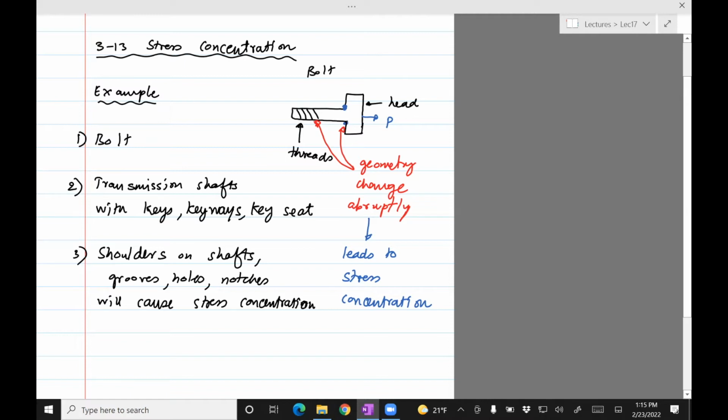The problem with finite element analysis is that it's based on finite elements. When you have stresses, they typically can go to a very large value, and finite element analysis cannot compute the stresses, especially when they blow up. So finite element analysis fails to predict stress concentration exactly. It does to an extent, but it can't really give you the exact stress.